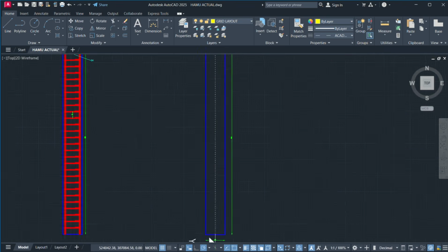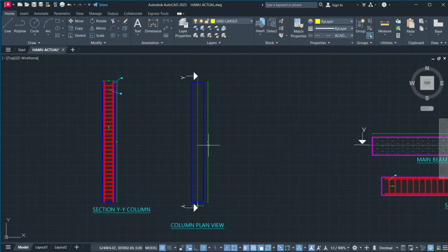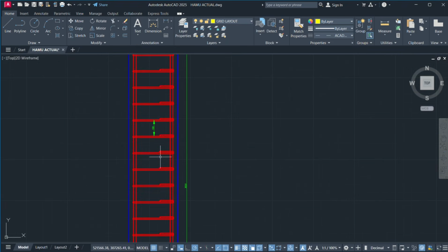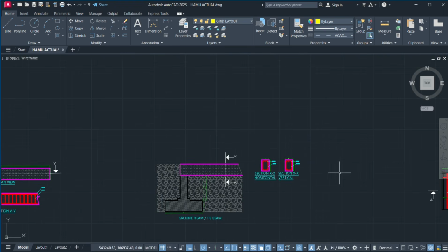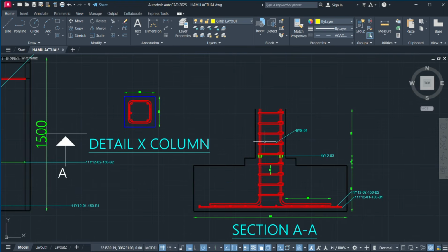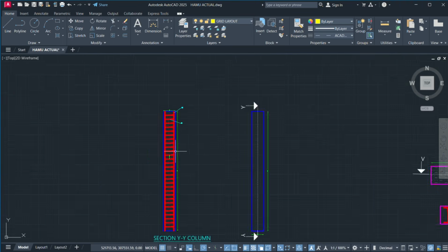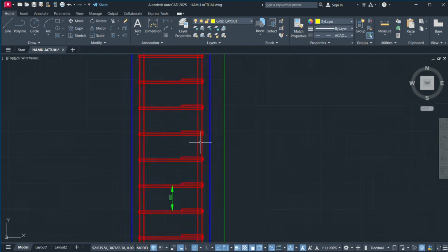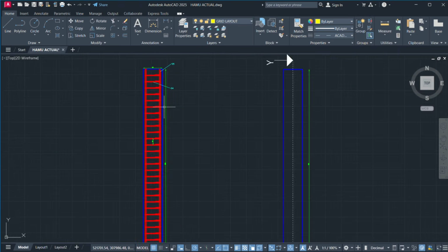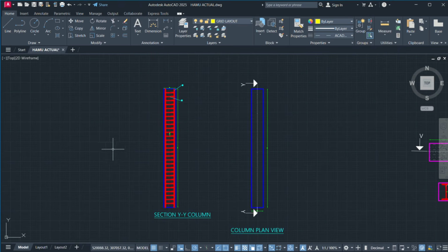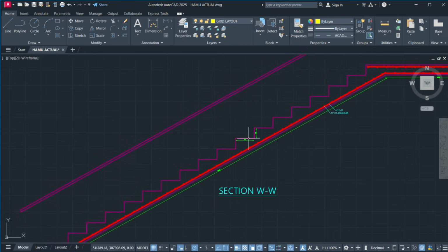So next up now will be the column, sorry. For the column, you're actually going to give it a distance of 3000 millimeters, just like this. This is a plan view. Then the section, it will be the same thing you had done here on this part. You're going to do it again on this side. Now these ones should be Y12, then these are Y8. Now you just start tying them around, just like I have explained on the pad.